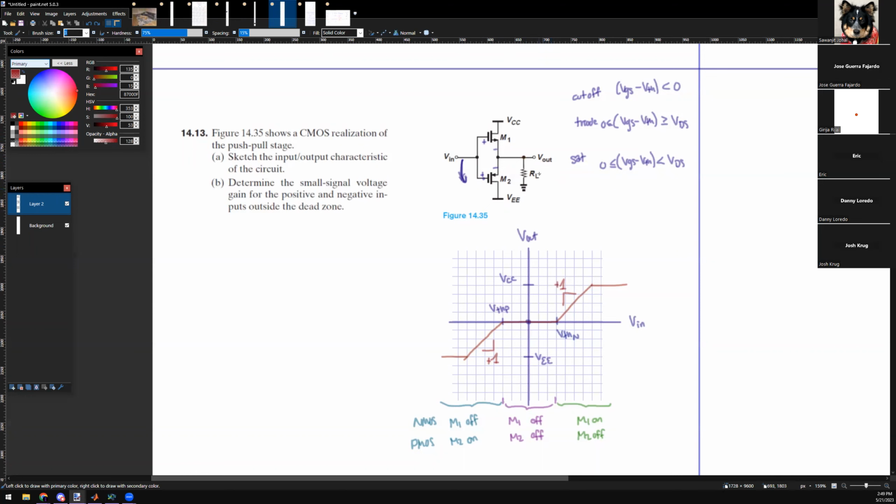What you were going to propose was that if you put a DC bias, technically you get the gain, but at the cost of a DC bias on V out, which means you're always drawing current through your speaker, and your speaker's going to burn. Your speakers rely on their own motion: with a high power speaker, you rely on its vibration of air to cool itself off.